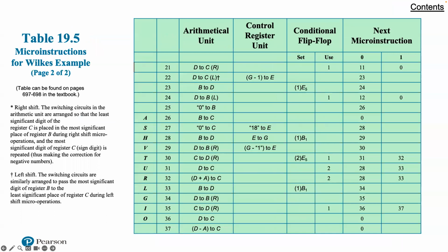The principal advantage of the use of microprogramming to implement a control unit is that it simplifies the design of the control unit. Thus, it is both cheaper and less error prone to implement. A hardwired control unit must contain complex logic for sequencing through the many micro-operations of the instruction cycle. On the other hand, the decoders and sequencing logic unit of a microprogrammed control unit are very simple pieces of logic.